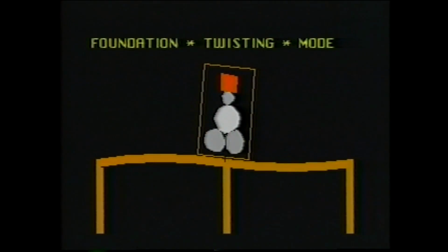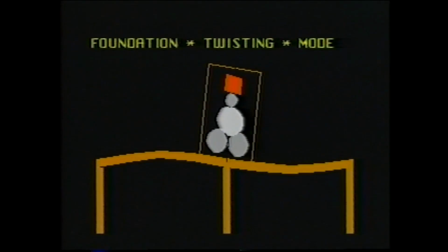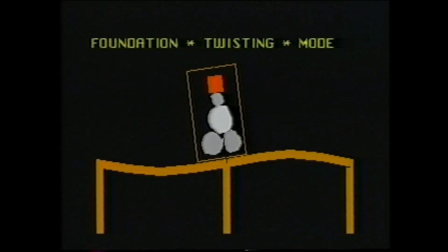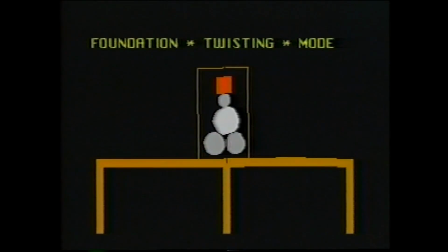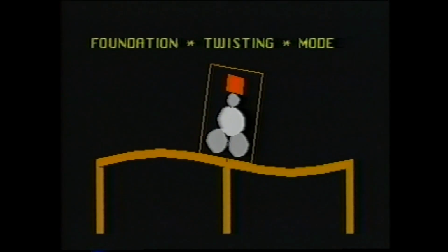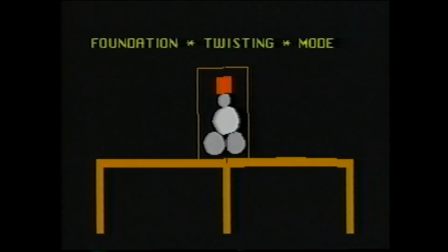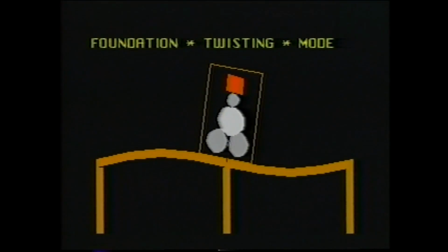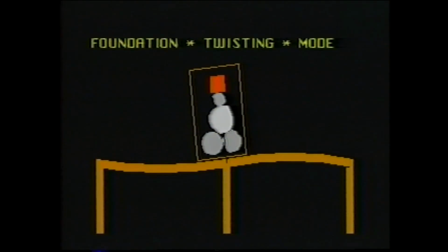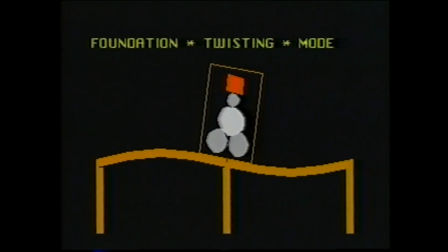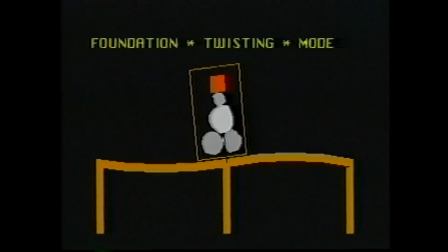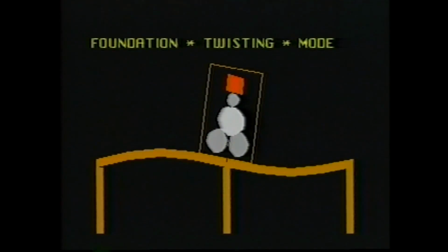Twisting modes are easy to identify because the flooring vibrates more in areas that are some distance away from the winder. Fortunately, twisting modes can be reduced somewhat by placing jack posts under flooring that experiences large vibration. However, this approach will only go so far because the fundamental problem of inadequate foundation stiffness has still not been addressed. As seen in this and the following mode, conventional column foundation design is often inadequate for winders.